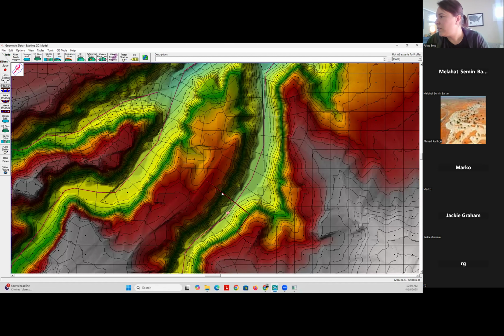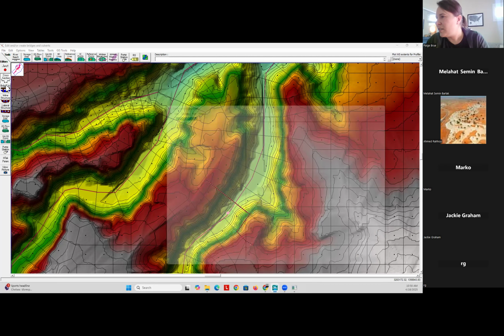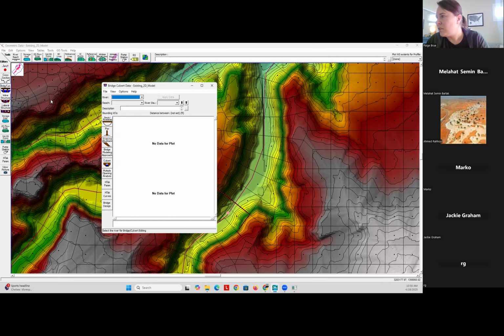And it would come up with this. The thing that is different though that you have to consider is the weir equations when you're modeling it. If your model is going to pass through critical flow, just make sure you click use weir equation instead of use normal 2D flow equations.